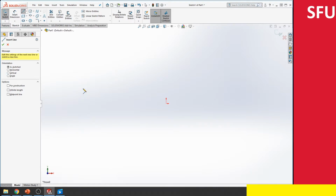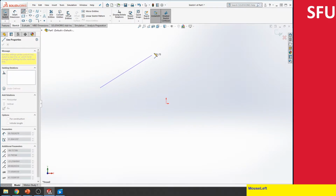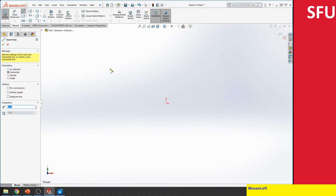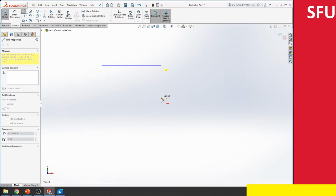So for instance, right now it says as sketched. What that means is if I create a line like this, and then as I try to move, it's going to be along the orientation I actually create the drawing at. If instead I create a horizontal line, then irrespective of what I try to do, the line is always going to be horizontal. And notice that as soon as I go very close to the origin, it draws a dotted line, and it says, hey, it looks like you're very close to the origin. Do you want to make sure that the line is limited by the origin? That's the additional constraint it looks at. We'll see what these constraints are in just a little bit.